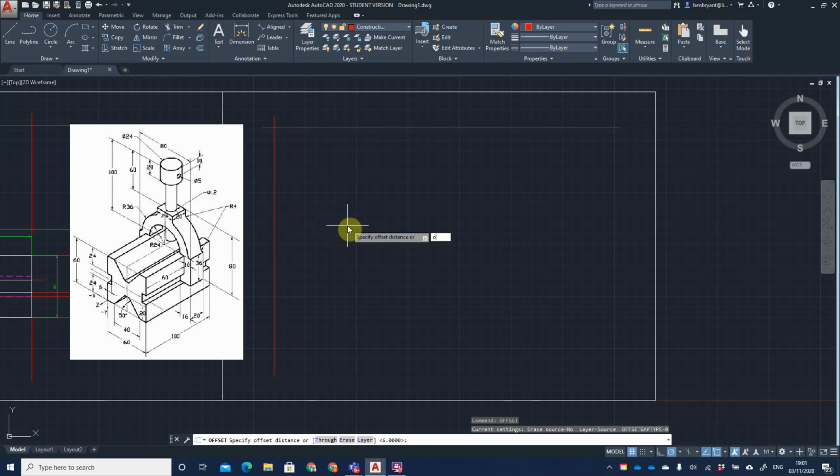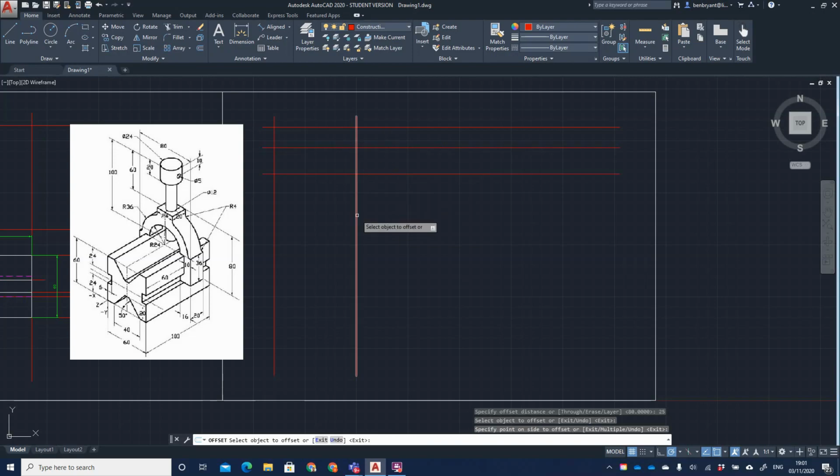So again, my first offset is going to be nice and simply 20mm. Okay, that's the first drop, and obviously it's 80mm in width looking top down. I'm going to stick the same 25mm as last time, which again is going to do left and right.